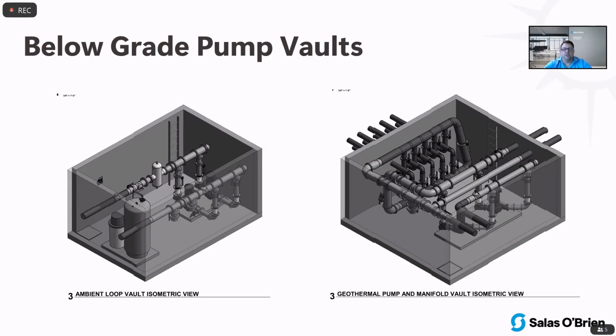And then where do you place these? Where do you have room for these? Generally in the street, you may not have room because of all the other utilities. So are they going to be placed in private property? If so, you have to have easements and land access agreements to access these vaults. So just thinking that all through about, number one, who's the owner? Who's going to own and operate and maintain the system? What are their capabilities? Where do you have space for this stuff? And then, what's the longevity? What are the service and maintenance implications of having something below grade? If this was in the street, it has to be vehicle load rated.